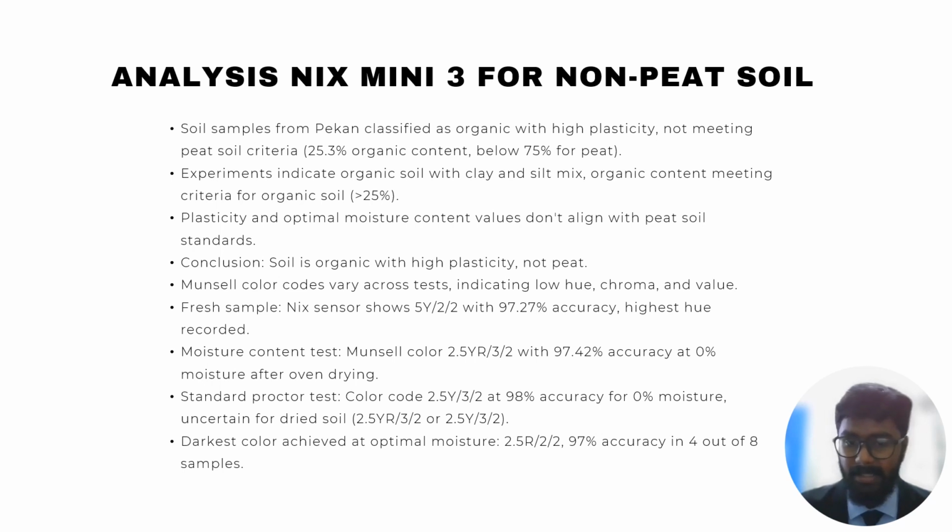The fresh sample from mixed color shows 5 hue, 2 chroma and 2 value with 97.27% accuracy, the highest value recorded. And the moisture content test is in the Munsell color chart 2.5 hue, 3 chroma and 2 value with 97.42% accuracy at 0% moisture content after oven drying, which is oven dry.